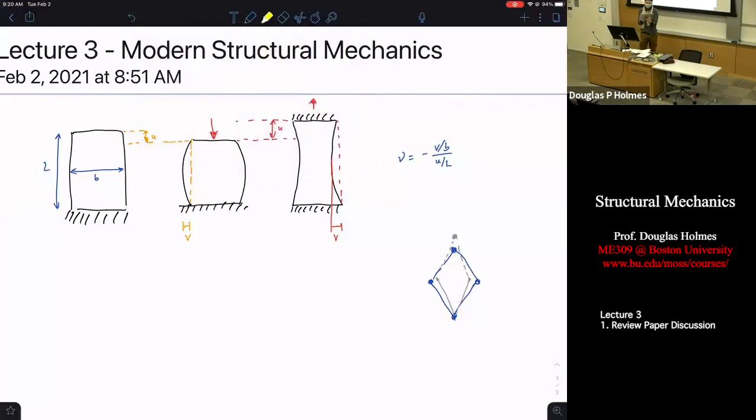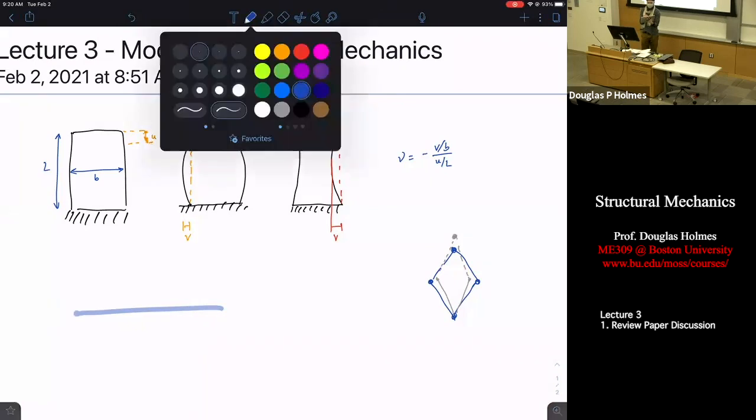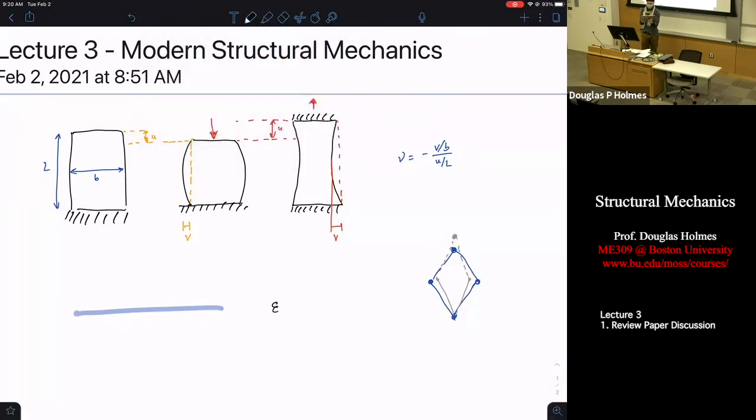So in bimetallic, you're familiar from mechanics of materials, I think, the idea that if you have a bar and you heat it up, then there'll be some strain, thermal strain, that's like the thermal coefficient of expansion, a material property that says as you heat it up, it's going to get a little bit bigger, or some strain per degree of temperature times the amount you've changed the temperature. Okay, so this is just basic mechanics of materials.